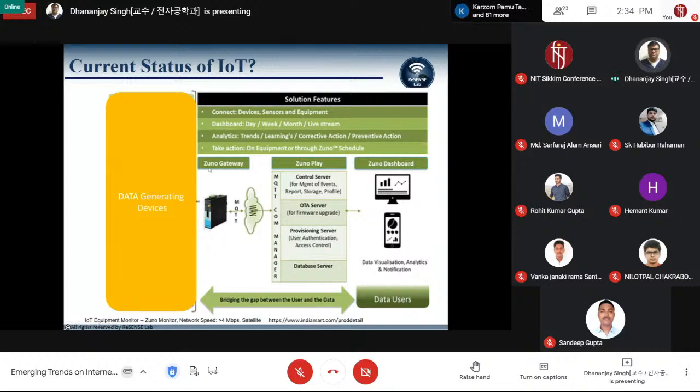The second one is the gateway. The gateway's role is that it must be compatible with the sensors' platform, and it must have internet connectivity, because we have to transfer the sensor data to the cloud. So we must find or choose a gateway. Gateways are also available in the market, you don't have to build one. But you have to create the software. You have to make the protocols, what kind of communication protocols you are going to select on this kind of device.